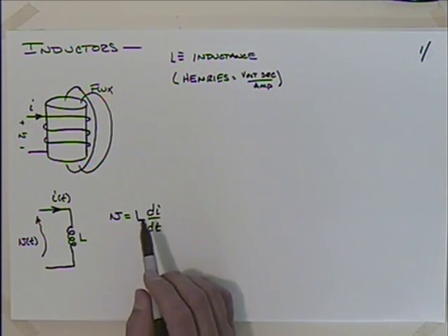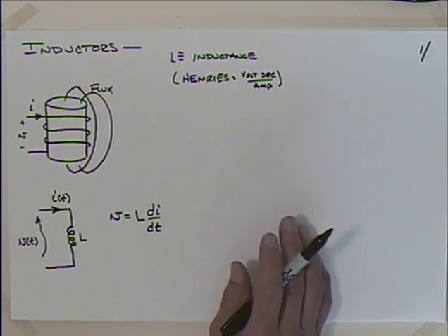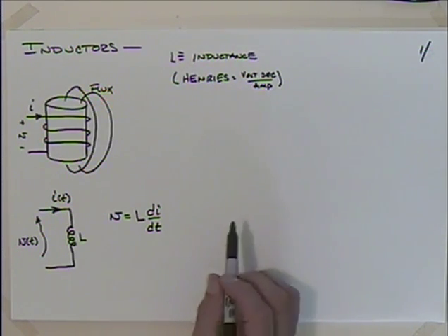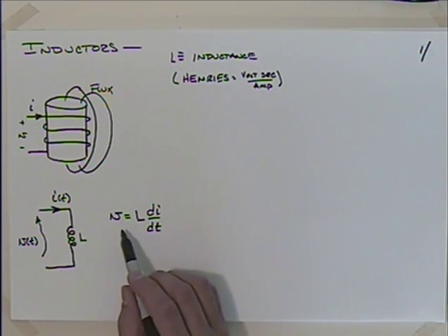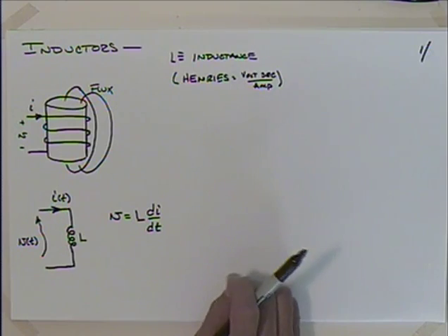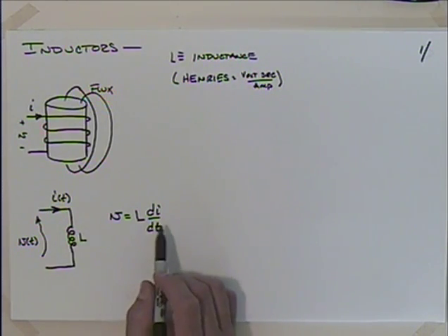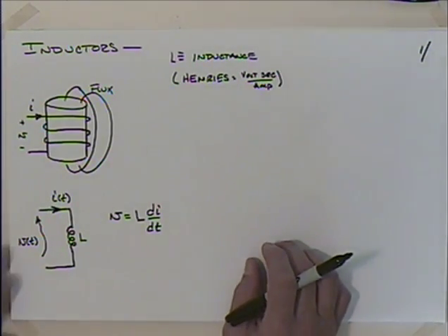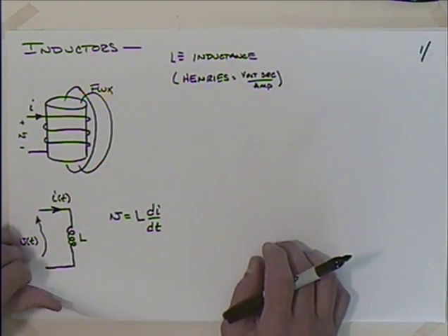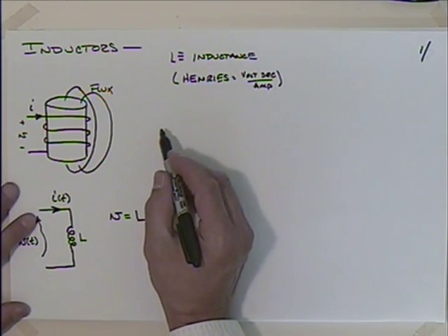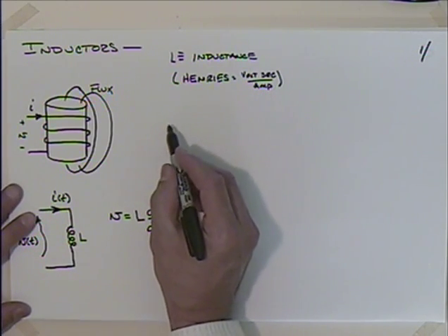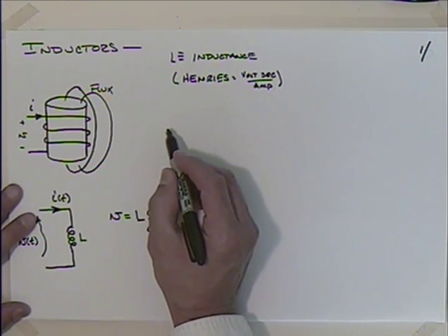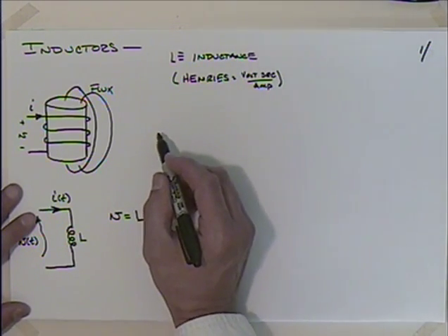We'll see a lot of similarities and differences. If we were in an English class, we'd talk about comparing and contrasting inductors and capacitors. Remember, with the capacitor, I was equal to C times dV/dt. Here we have V equal to L times di/dt. One of the things we should talk about is where we find these things. There are lots of places in electronics, filters and things like that, and we'll talk more about those next term.